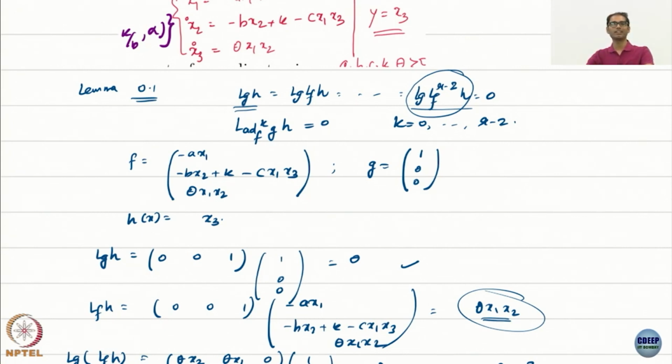So it's almost like saying, I mean, unfortunately I will not have time to talk about those, but there's this notion of differential flatness also, if some of you have seen this. Basically it says that you take a certain number of flat outputs, and all the system states and the inputs can be represented as these flat outputs and their derivatives, right. So again this is also a similar notion, a property of the input output system, somehow making some part of the system linear, so the behavior will be linear.